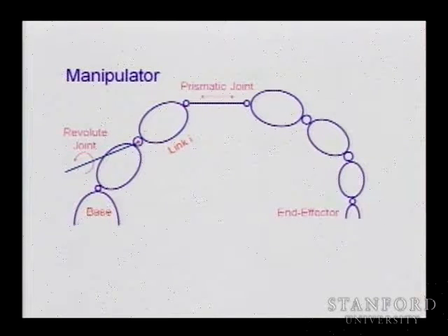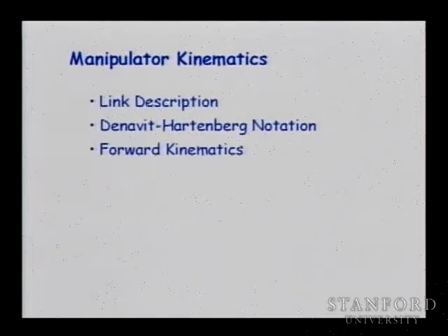And between these two objects, you have all the links that are going to carry the end effector to move it to some location. And the question is, how can we describe this mechanism? So we will see that we are using joints of different kinds, joints that are revolute, prismatic, and through those descriptions we can describe the link, and then we can describe the chain of links connected through a set of parameters.